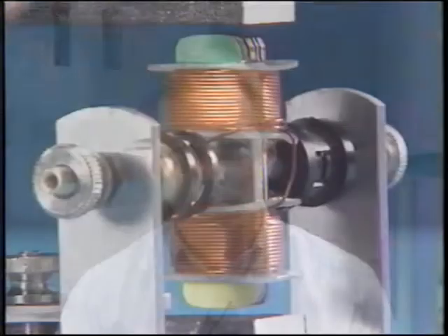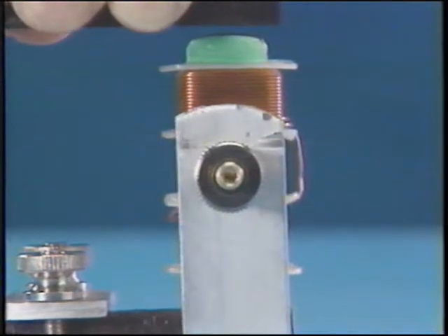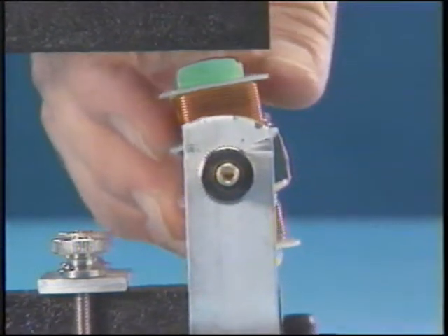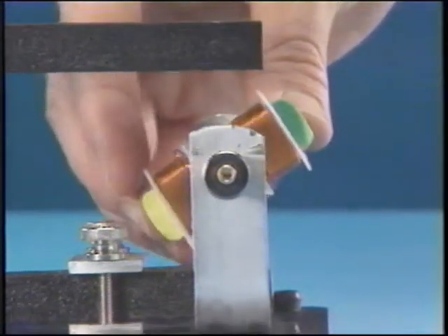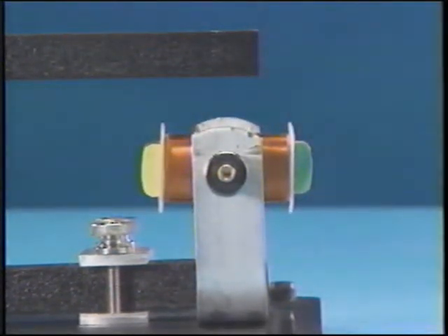spinning. As the coil revolves through the magnetic field created by the two magnetic poles, it cuts through the flux lines at different angles. To start, the coil rotates to a horizontal position with yellow on the left and green on the right. This graphic shows that for this instant, the coil is positioned parallel to the magnetic lines of force as represented by the arrows. At this point, no voltage is induced because the magnetic field is not being cut.